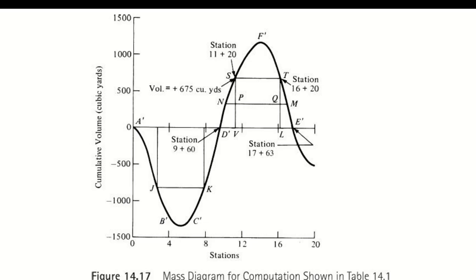I need the quantity of material at these stations. One of the stations is 1120. The other one should be 500 feet from it, right? Because he agreed for 500 feet. So 1120 plus 500 is 1620. So I need to get the ordinate at both the stations. Now, I'll go to the table.